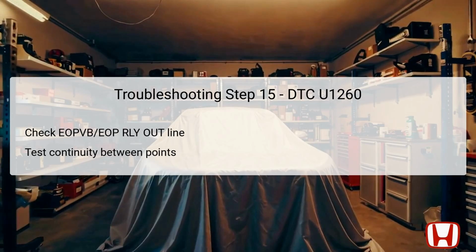Maintaining the vehicle in the off mode, ensure that both connectors are disconnected while testing for continuity. If continuity checks out, it indicates that the EOP-VB EOP-RLY out wire is functioning effectively. However, if no continuity is detected, it reveals an open circuit that requires immediate repair.